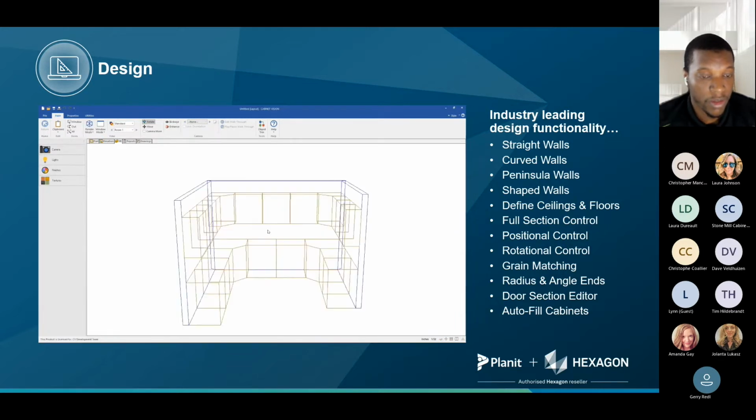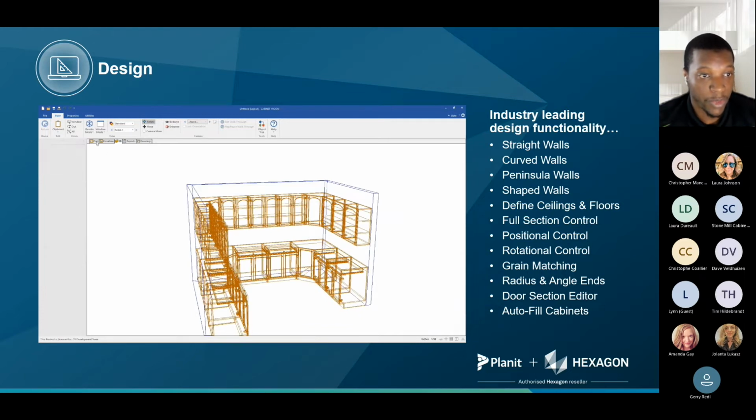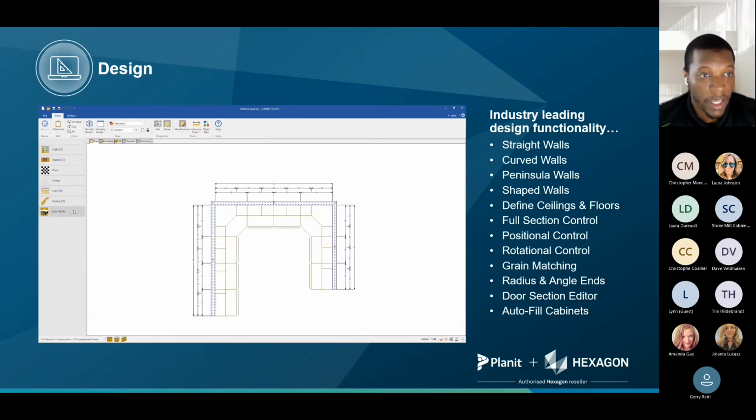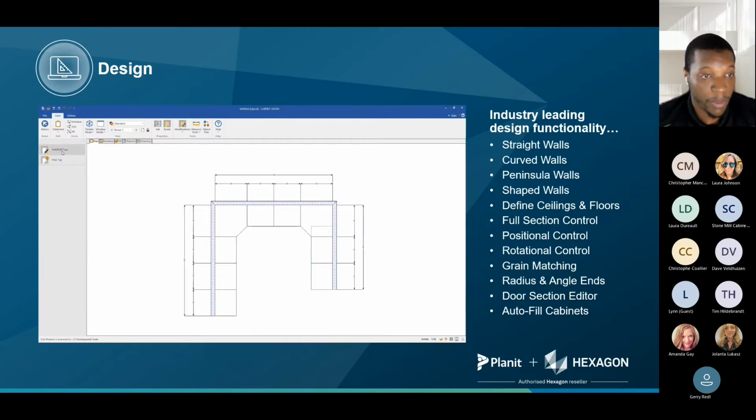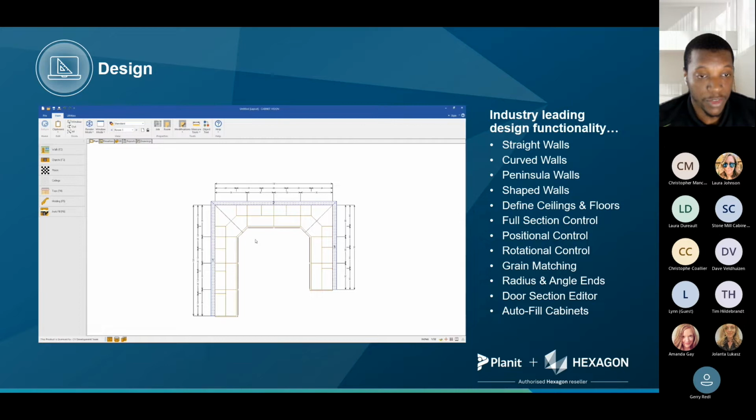So now in the 3D view, you will see basically the end result of my room layout, and you can go from wireframe rendering to texture rendering as well. And the other thing is, if you want to add countertop and molding, it is as simple as going to the auto build top or molding tool and having the software create your countertop for you. And of course, you can still manually go edit the countertop shape as well to make any changes, extend, create a radius as well on your part as you want to customize it.